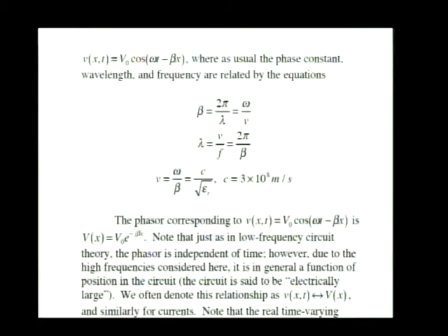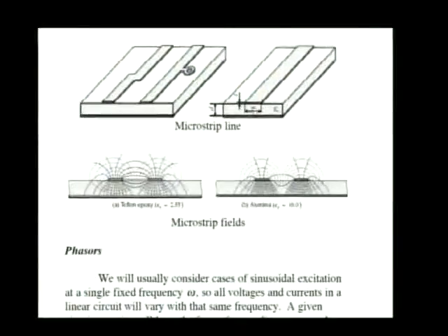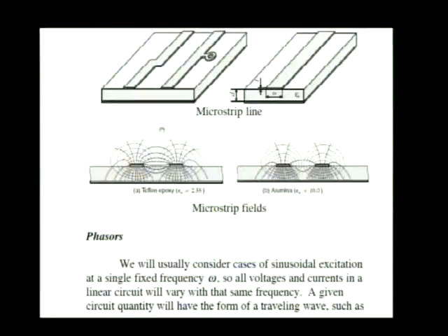How about in the microstrip? Epsilon r, what would I use? Let's check out that picture of a microstrip. I've got 2 possible epsilons I could use here. Some of the fields are in the substrate, where epsilon r might be, let's say, 2.25, like shown here. But some of the fields are up here in air. Epsilon r equals 1 for air.